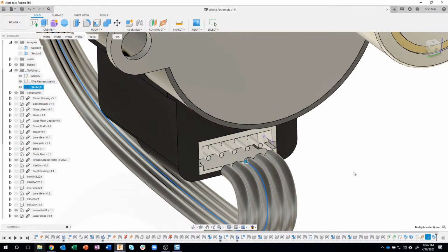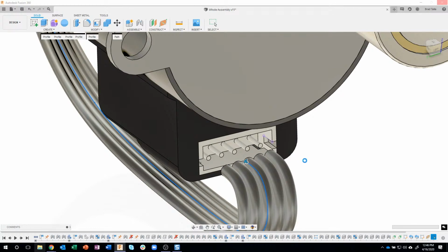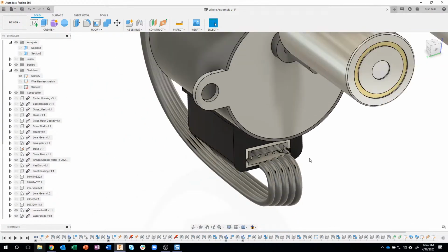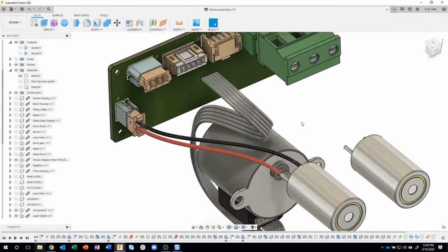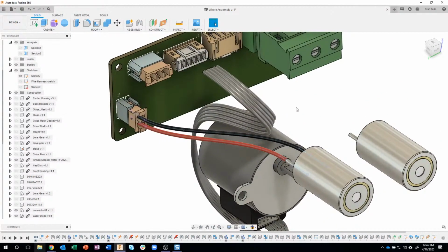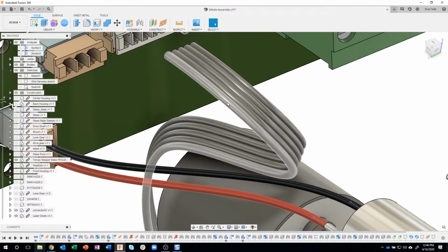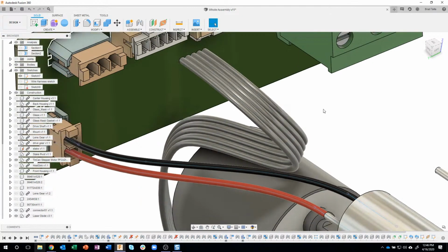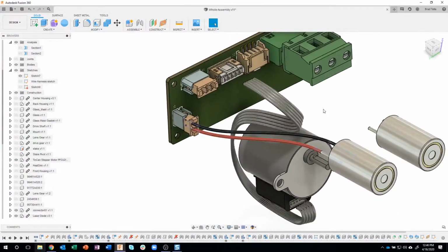And I've now created this wire harness. Now, like I mentioned before, this is going to be all one body because they're touching each other. But that's okay. Now, you might be excited and say, oh, let's add the color to it right now. We're not going to. We're going to wait till the end because we're going to be coloring individual faces instead of individual bodies. You'll actually notice, for example, this one looks good, but as I move across, it's not highlighting this face down here and stuff. So we're going to have to apply our appearances to certain faces.